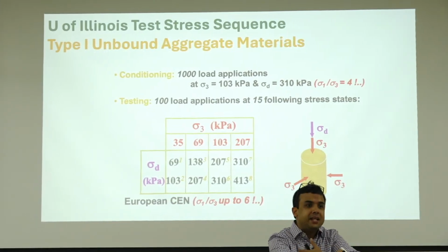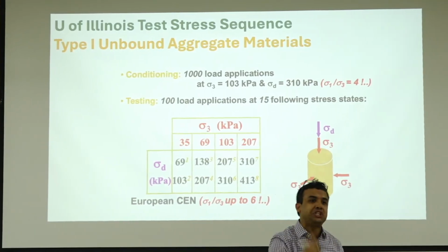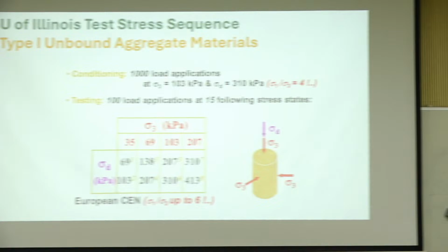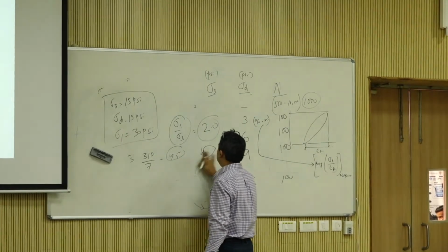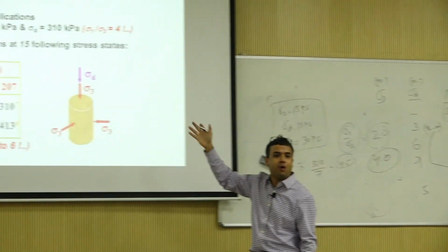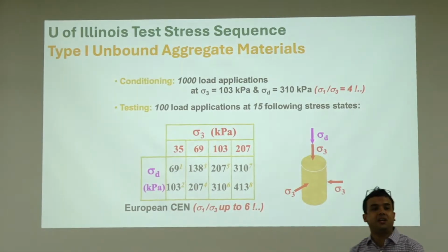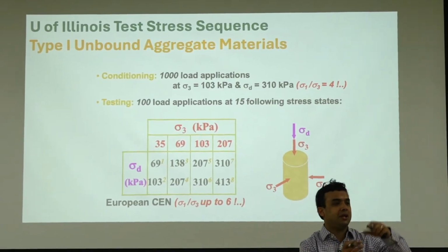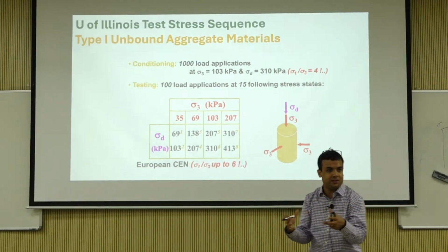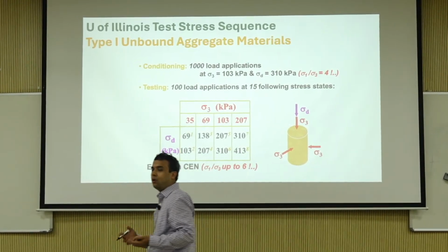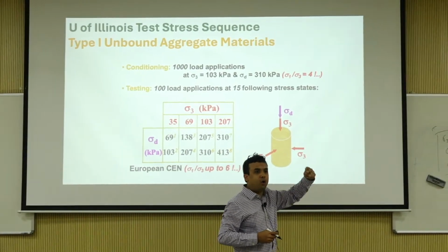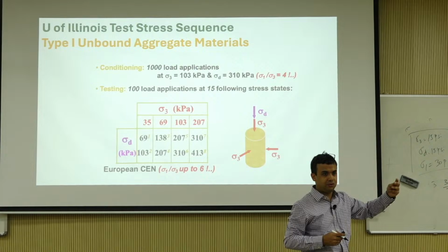So it's holding the material really well, but it is pushing it really hard to pack it really well and then get a well compacted, well conditioned resilient modulus response under this torture index of 4.0. So basically, remember yesterday how we calculated subgrade soils? They are not very well confined because it's only about half a psi of confining pressure we calculated yesterday. The whole idea is during compaction, the more you push it, the more you condition it, the more of a resilient behavior you will get. So that is how this was defined.